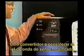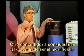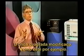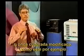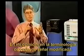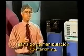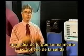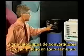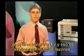Another type of inverter output waveform that we want to consider is what's often called modified sine wave or modified square wave. An example might be this Heart Interface Freedom 20. The terminology of modified sine wave, to me, is a little bit of marketing manipulation. I would rather call it a modified square wave. It gives more of a sense of what you really get from the output. But these types of inverters are widely used worldwide in photovoltaic applications.